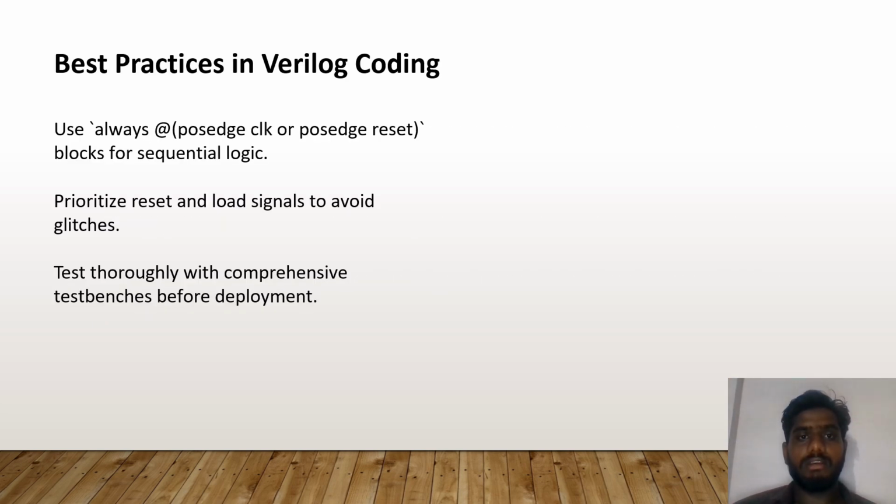Best practices in Verilog coding. Use always at the positive edge block for sequential logic. Prioritize reset and load signals to avoid glitches. Test thoroughly with comprehensive test benches before deployment.